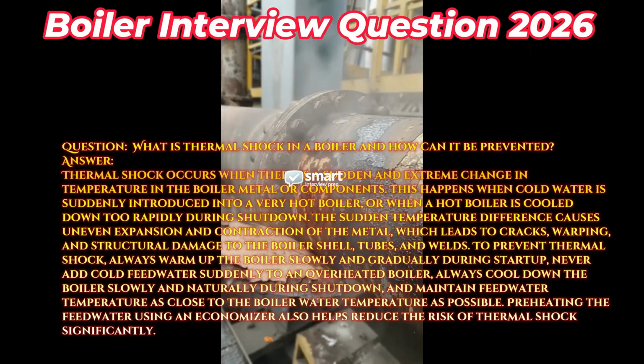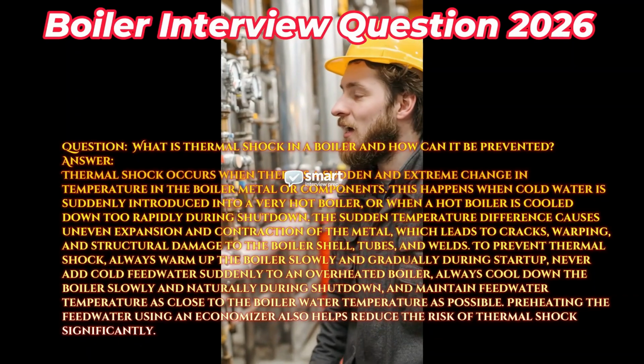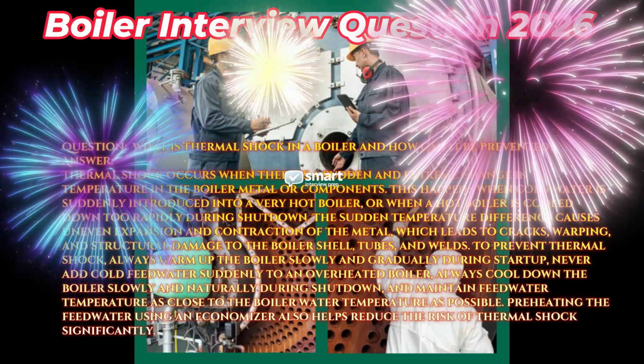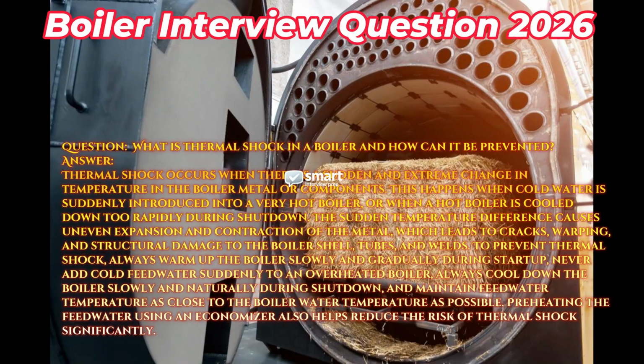The sudden temperature difference causes uneven expansion and contraction of the metal, which leads to cracks, warping, and structural damage to the boiler shell, tubes, and welds. To prevent thermal shock, always warm up the boiler slowly and gradually during startup. Never add cold feedwater suddenly to an overheated boiler.